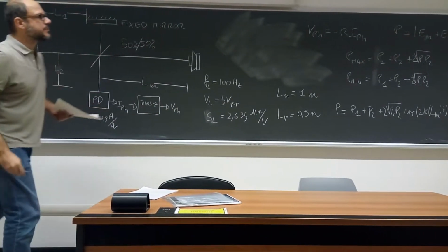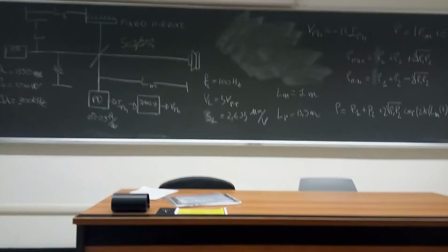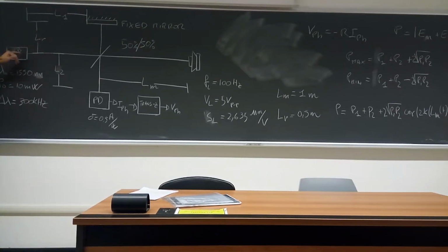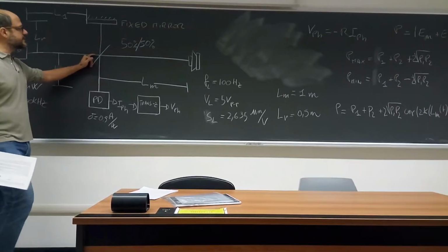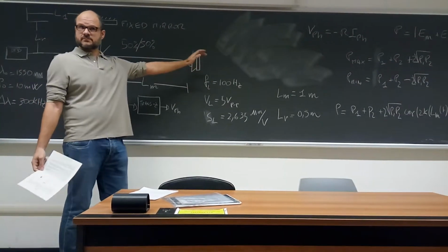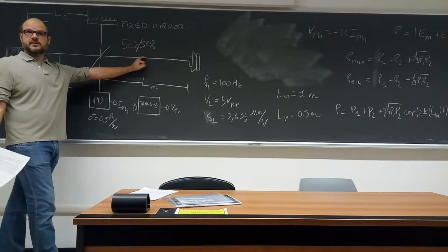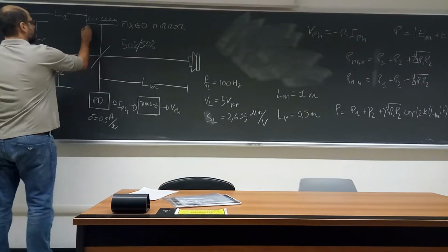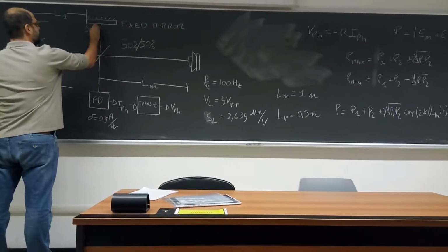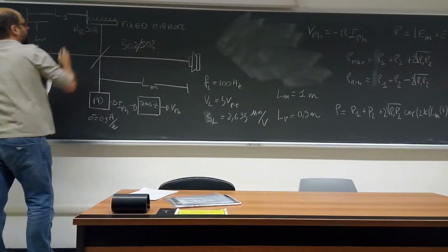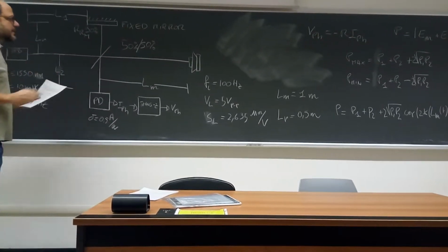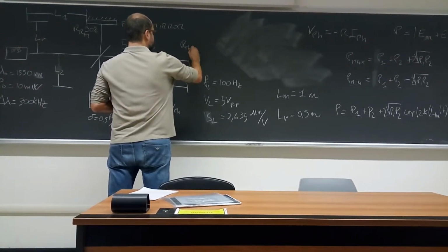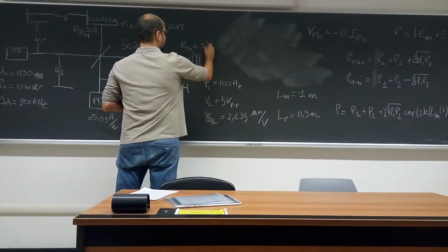So, for example, let's suppose that P1 is related to the measuring path. Okay? So what do we have? We have P0 that is emitted from the laser. Then half of the power is transmitted toward the loudspeaker. Then we have 5 milliwatts here. And then coming back, sorry, there is another point. I have to tell you that the reflectivity of the fixed mirror is 90%. So the reflectivity of the reference mirror is 90%, and the reflectivity of the measuring mirror is 5%. Okay?